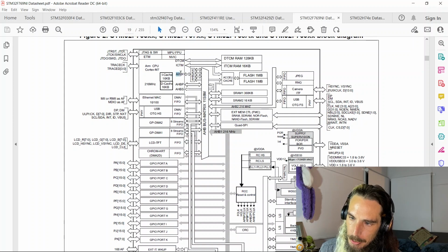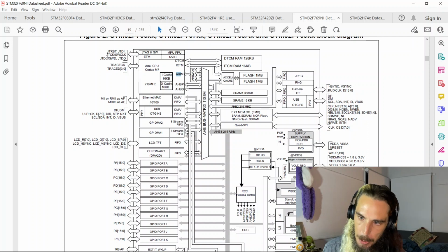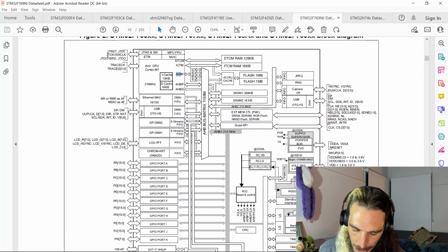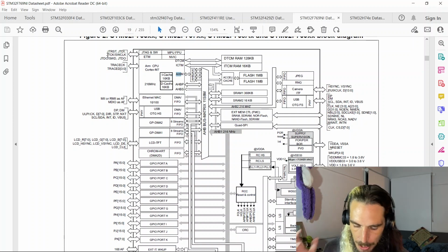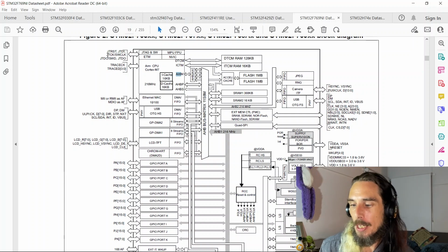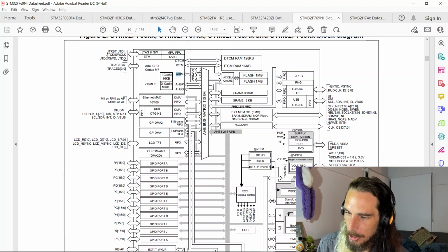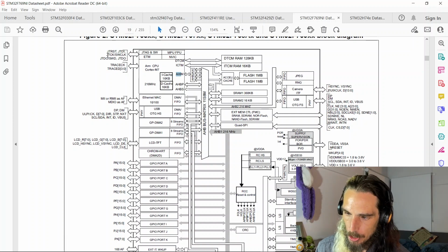And we've also got an AXI connection, or AXI, which is a more advanced bus than the AHB. So the Advanced High Performance Bus, or AHB, and then more advanced than that is the Advanced Extensible Interface, which is another form of connection that was developed by ARM, which you'll typically find quite regularly in ARM processors for smartphones and that sort of thing, where even more performance is required from the bus, more features and things like that.